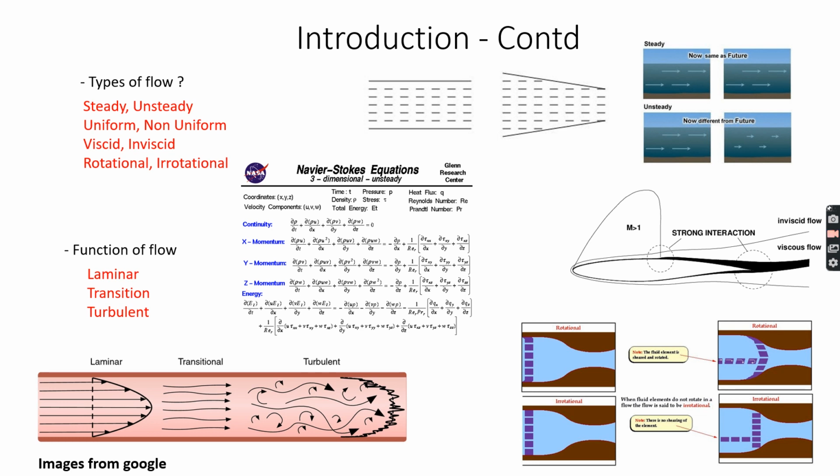And flow on a flat plate, which is a very famous case for building up the Blasius boundary layer and all that, tends to go up to 10 power 6 of Reynolds number for turbulent. Before that, from 10 power 5 or 10 power 4 to 10 power 6 it's transition, and before that it's the laminar part. So it's case dependent and it's a function of the flow.